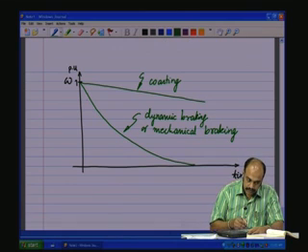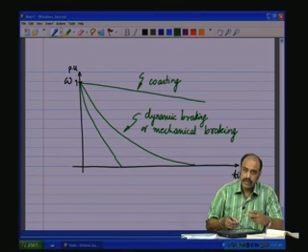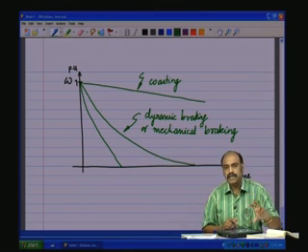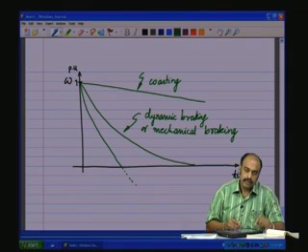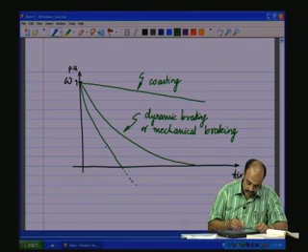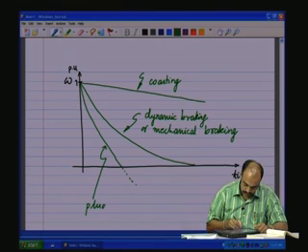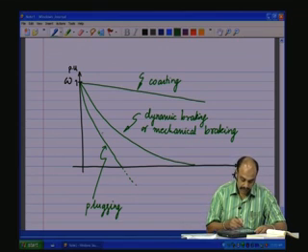Then the third one would be the plugging, and that would be very fast, and you should see that it comes to 0, and then after it comes to 0, because you are applying EP in the reverse direction, it will try to change polarity and start rotating in the reverse direction, but you have to switch off at the point when omega becomes 0. So, this would be plugging. So, plugging would be the fastest.